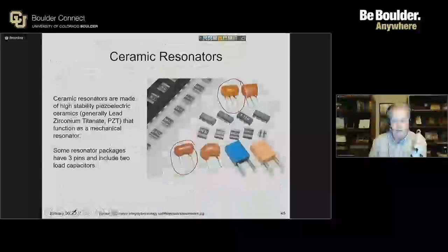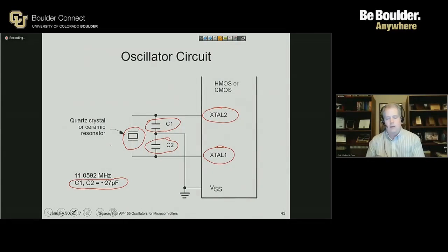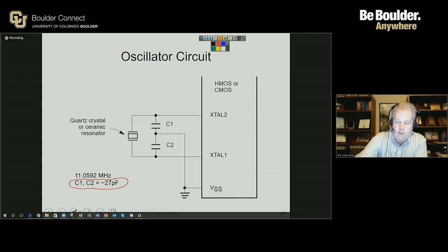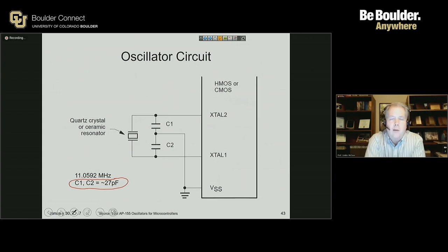Let's take a look at that circuit again. Here's my oscillator circuit. If I turn on power to my system and I want to test to see whether or not my oscillator is running, can I just take my oscilloscope probe and connect to XTAL1 or XTAL2?